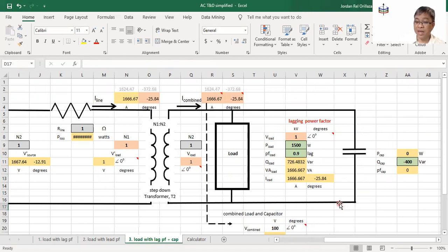And the key here is basically, if you pick a load here with a low power factor, suppose we have a 0.05 power factor there, then this is the requirement Q. This load here requires this much Q, reactive power. But what we recommend is you provide a capacitor that will provide that reactive power there.